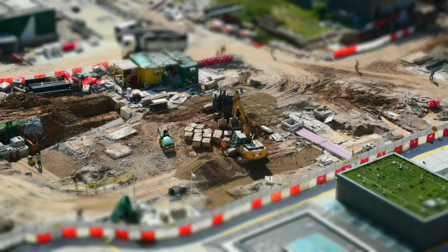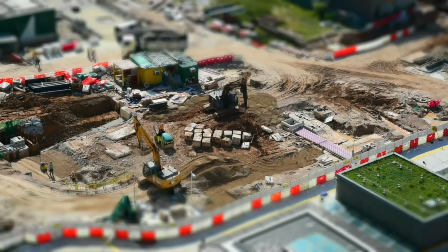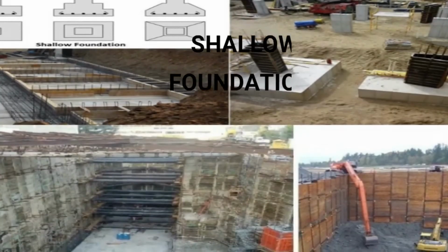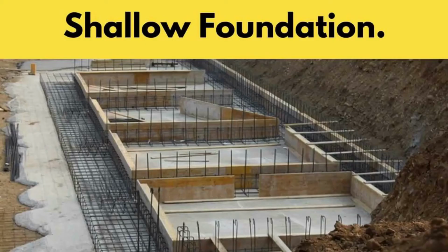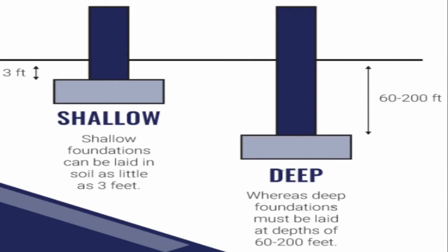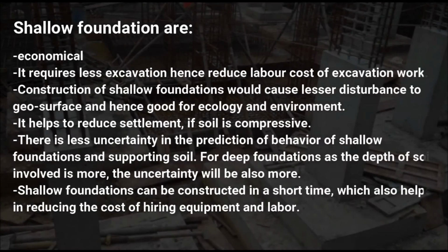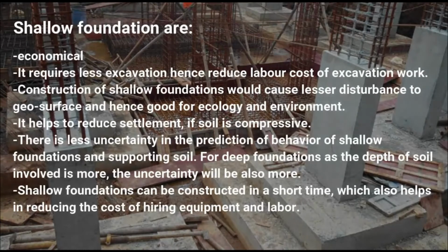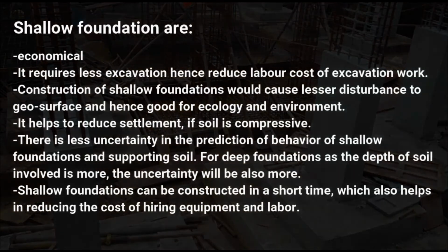In the structural engineering world, there are two common categories of foundations in building design, namely, shallow foundations and deep foundations. Shallow foundations normally range from 1 meter to 3 meters deep from the natural grade level. They are more economical than deep foundations, since a lesser volume of excavation is required because shallow foundations normally rest in hard strata that are located just near the ground surface.